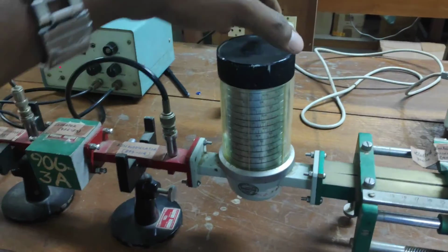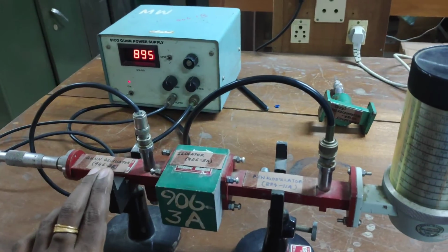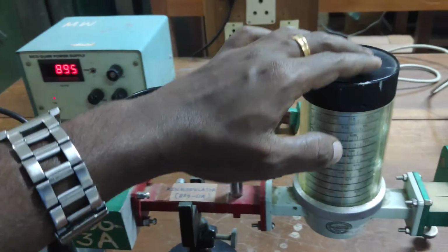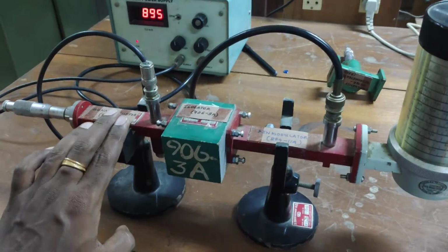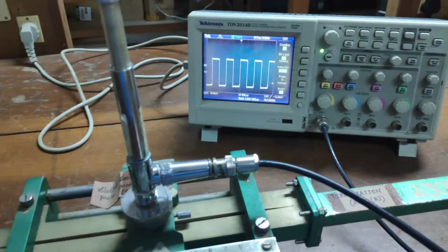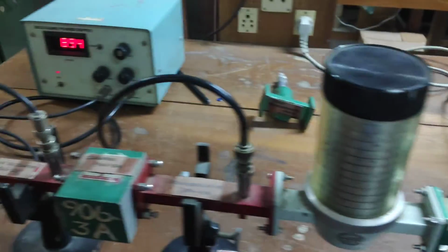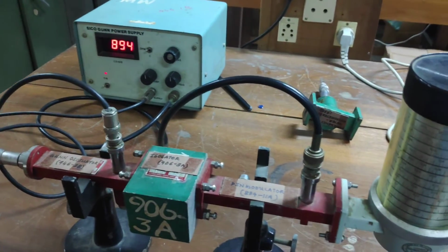If we measure the tuned frequency, we can identify our transmitted signal frequency. When the tuned frequency is equal to the transmitted signal frequency, we will observe a dip in the output signal, or a reduction in the output signal. The transmitted signal frequency is fixed, we can't vary that one.